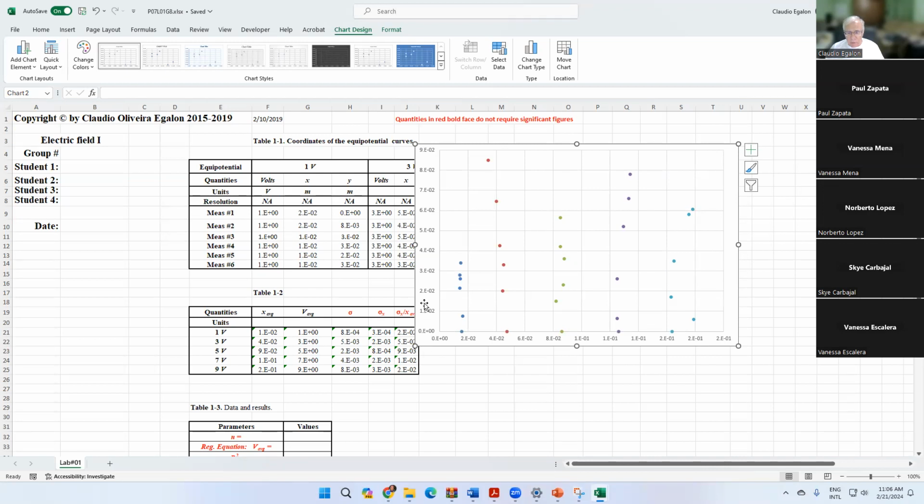Okay, note the axis numbers, 0, 1, 2, 3, 4, 5, 6, 7, 8, 9 along one axis, and 0.2, 0.4, 0.6, 0.8 along the other. Instead of this exponential format, the scientific notation, which I don't like, I put it in regular number format. So you go ahead and click right in here along this axis, the numbers along this axis, and double click.